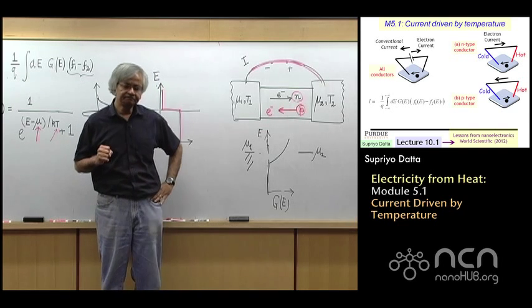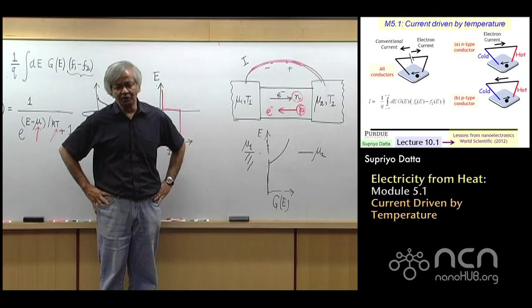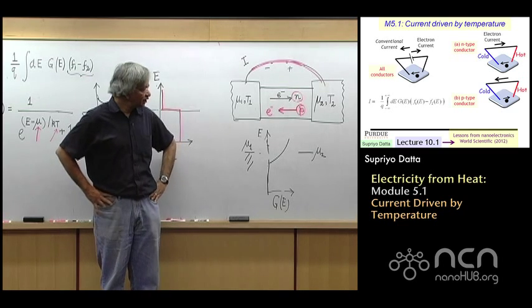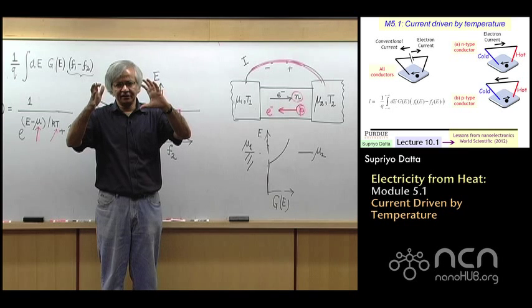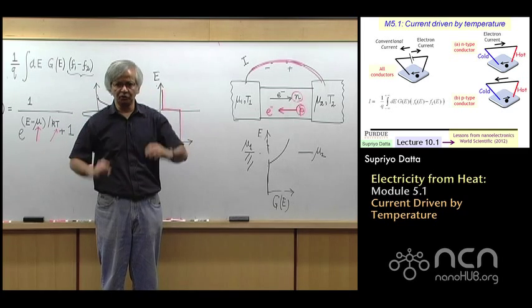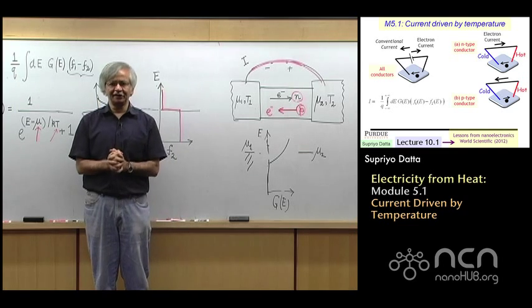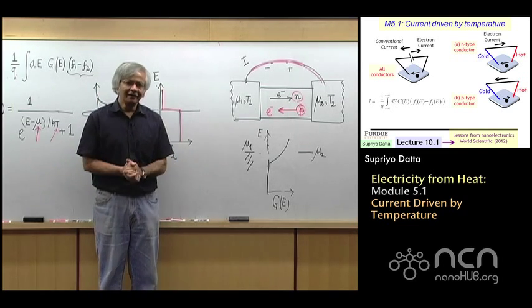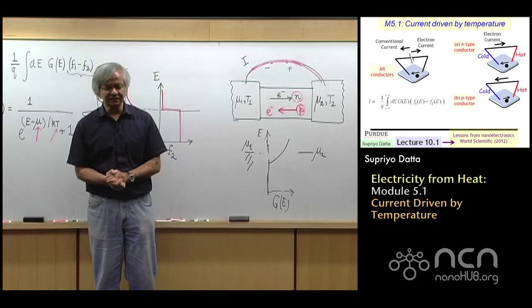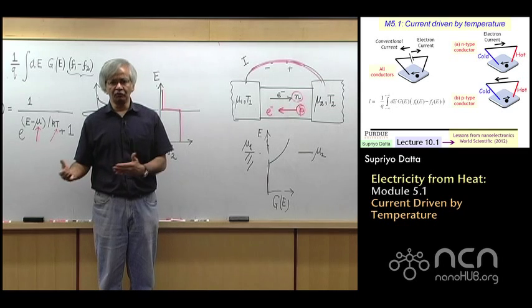And the reason is that, those of you who are familiar with holes, as you know, this concept of holes is really just a conceptual tool. In other words, when you have a band full of electrons, it sometimes may be conceptually easier to keep track of the empty spots, which you call the holes. But in practice, there is no doubt that what actually moves inside any conductor, metal, semiconductors, is actually negative charges. It's the electrons that move. It's just that under certain conditions, it may be conceptually convenient to think in terms of holes.